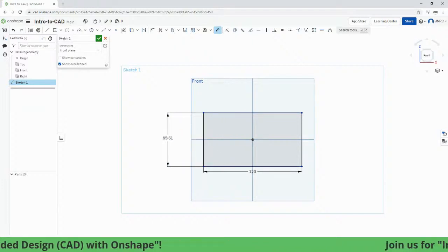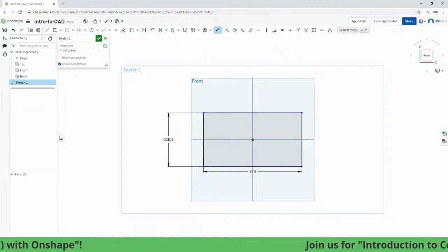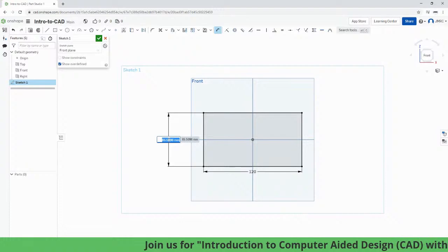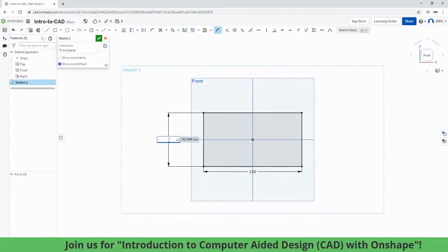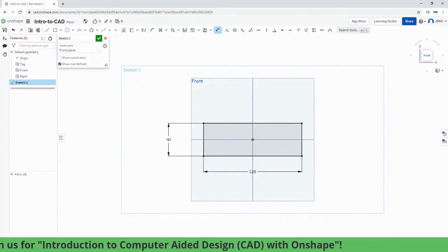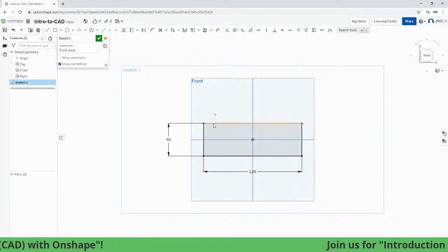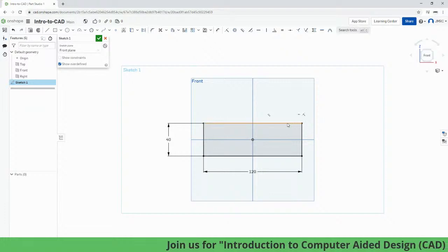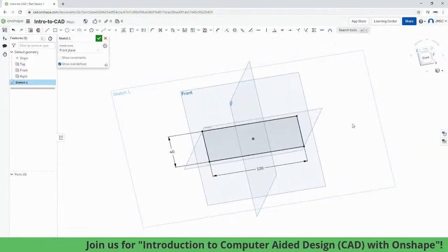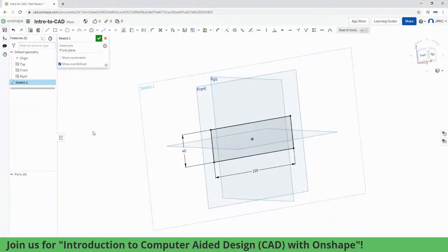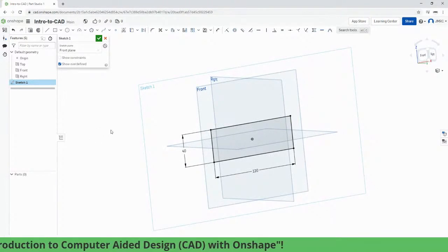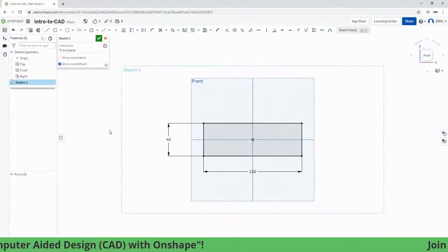So next, let's place our dimension over here. I'm going to left click to place it here. And I'm going to type in 4P. Okay, so once more, notice it turned into black. And as I hit escape to disable dimension, notice as I left click and hold to force this horizontal line to move, these are now all locked in place. Okay, so once more, hitting N to view normal to.